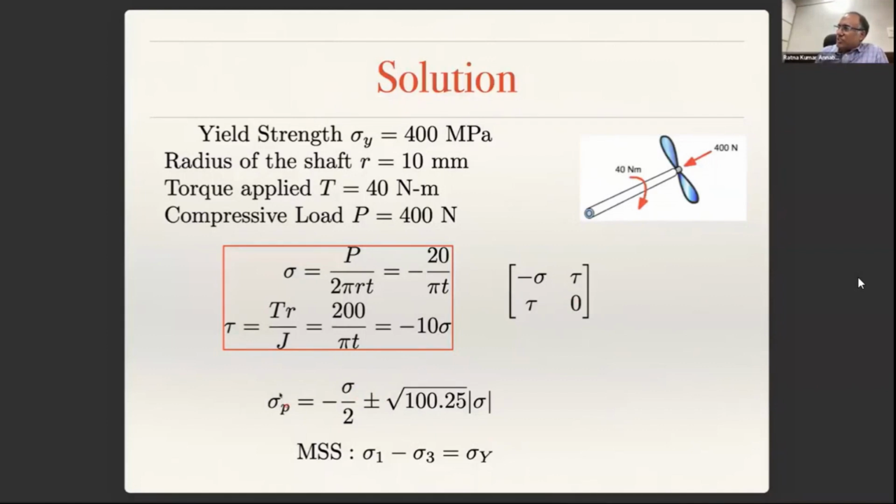So there are only two principal stresses, right? Definitely. The loading is two-dimensional because there is only axial stress in this direction and shear stress. So you can simplify that as a 2D problem. It is not a 3D problem. Although the problem itself is 3D, it can be simplified to 2D because the state of stress is only 2D. Can you see that?